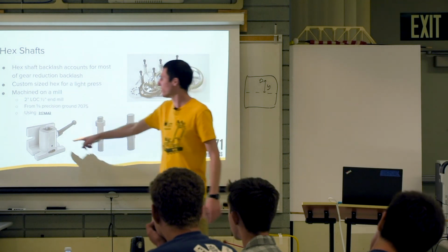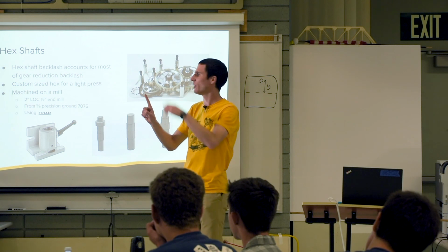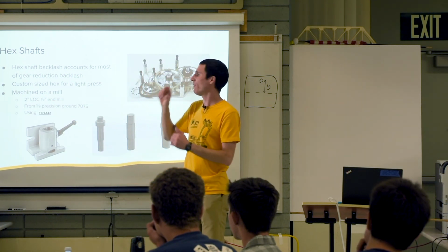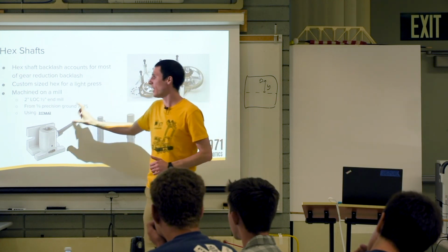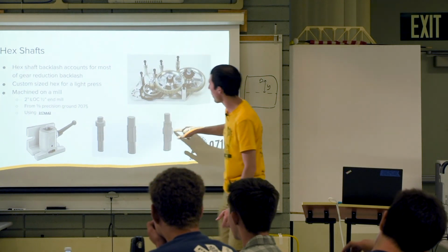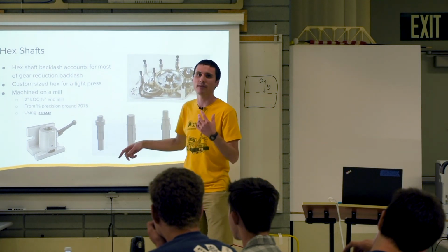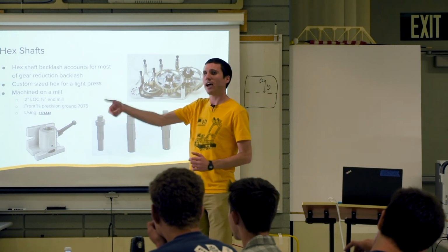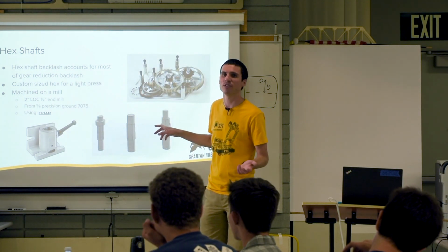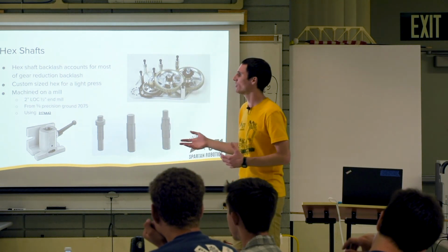So we take this and we plan on holding our shaft upright. We machine one side of it with a relatively long end mill. We designed for a 2-inch long, half-inch diameter end mill. We just machine one side, we flip it over, and we either hold it by the middle, which is sometimes why we integrate a spacer in the middle, or we hold it by just a hex or something like that. So we design for 2.5-inch long end mill, which means all of these shafts are under 3.5 inches long. That's one of the design constraints for machinability.